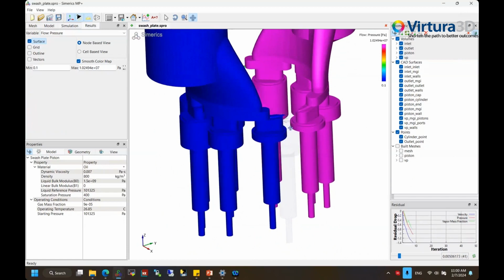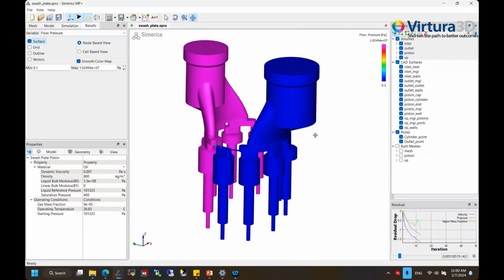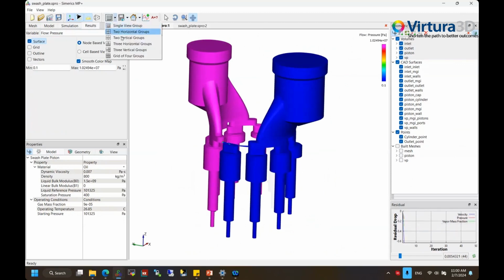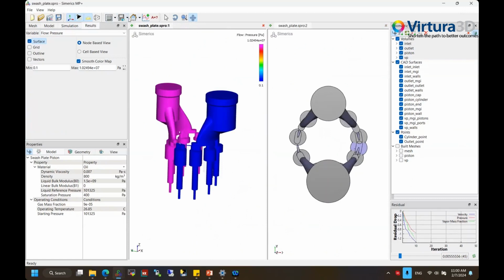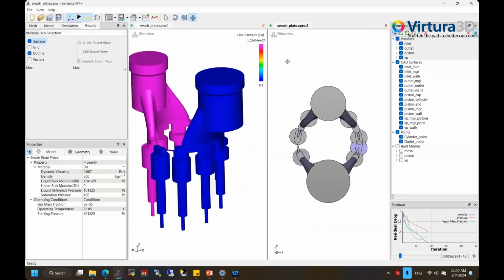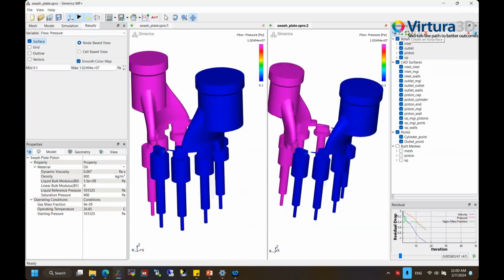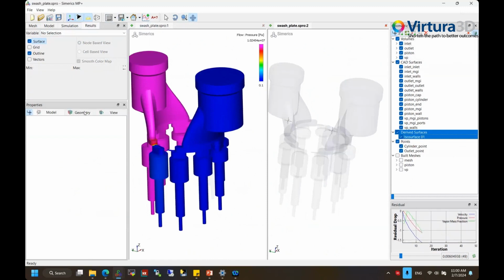It creates a strong jet. So this is the pressure distribution, and we can create another video to visualize the cavitation bubbles so that we can put those side by side. And we have this pressure, and then let's say I can create an isosurface of this total gas volume fraction. To create an isosurface, I just click this button and it creates this isosurface.